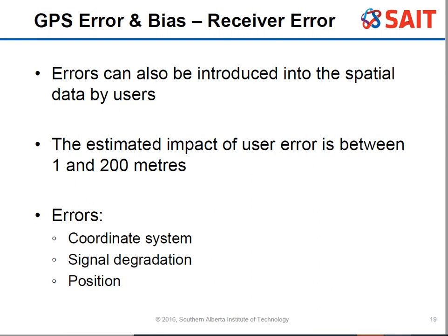The other thing is making sure that you are actually fully receiving all of the satellites. That is another error that we will often see. We call it fixed and float. Fixed means that it's receiving the full code. It now knows exactly where it is with respect to those satellites, and so it's able to calculate its position. If you have a float situation, you're going to be off by a couple hundred meters, and it's not going to be able to correct for itself, and then you end up with an additional error.